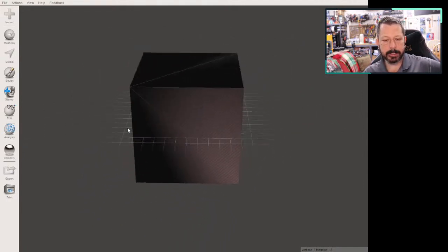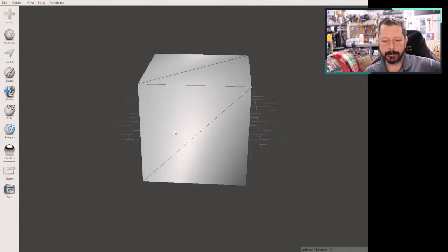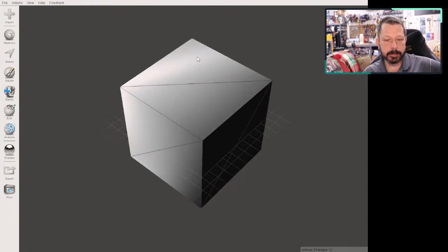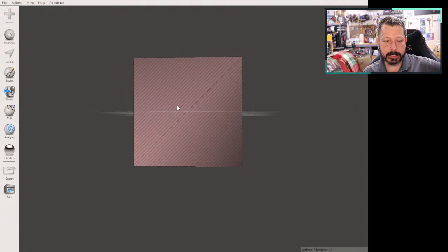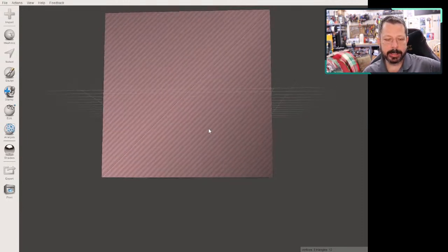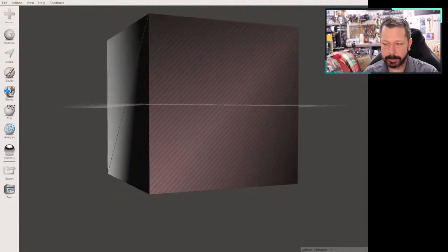So this is what it made. All that code that we were looking at makes a cube, and it's got flipped normals over here, so that's an issue. Each face of the cube is 2 triangles. Now these little red lines here, what that's showing me is that that's actually the back side of these faces. These faces in an STL file do not have thickness. They are just a plane with no thickness. And this is actually the back of the plane.